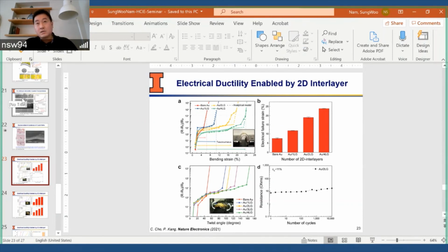In our case, the crack is dominated or guided by buckling. So if we want to control the crack behavior, we probably first want to try to control the buckle. When we can control the buckling behavior, we probably can tie that to cracking. So as I said, it's possible, but we just need to think about it in a slightly different way. Instead of an indent, we create different features on the substrate that could guide the buckling behavior. And of course, that could enable different crack formation in different sizes.